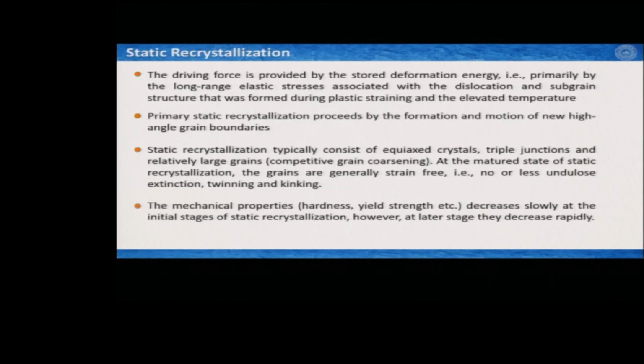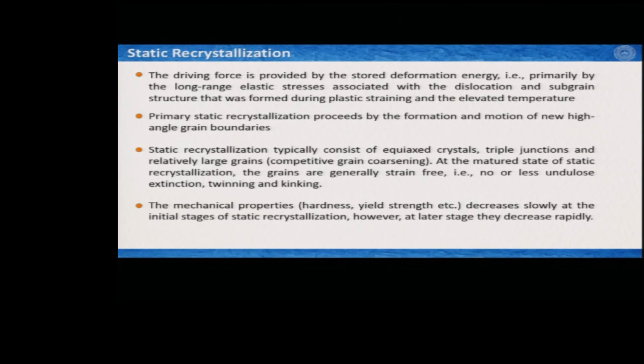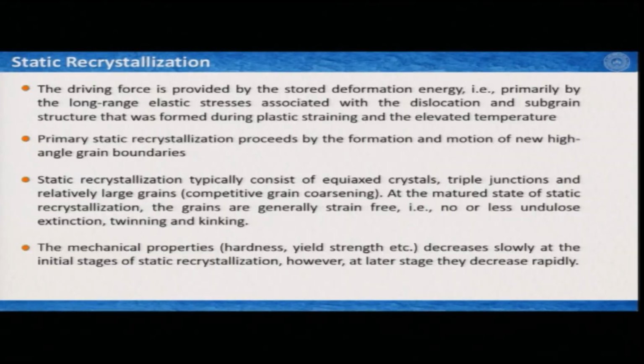So, these are the characteristics of static recrystallization. As you can see, it is written here, the driving force is provided by the stored deformation energy. So, your sigma internal, that is primarily the large or long range elastic stresses associated with the dislocation and subgrain structures that were formed during plastic straining, and certainly number 2 is the elevated temperature. So, your internal energy and elevated temperature. Primary static recrystallization happens by the formation and motion of new high angle grain boundaries.